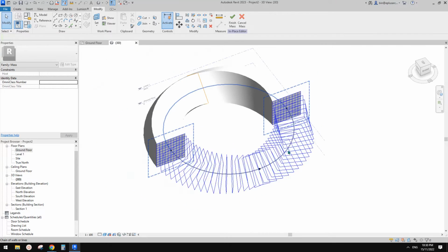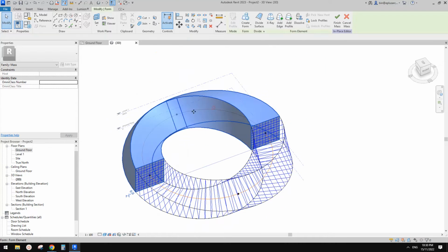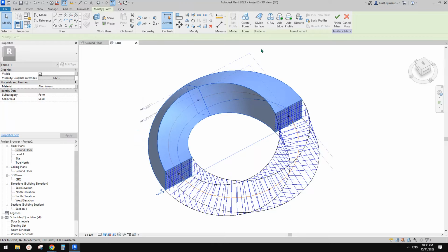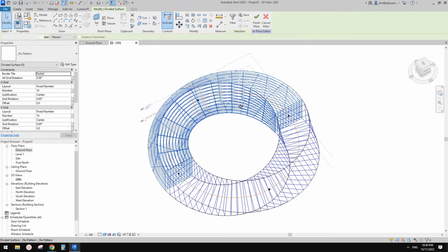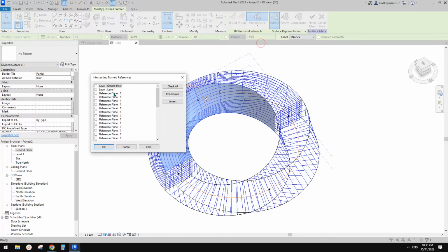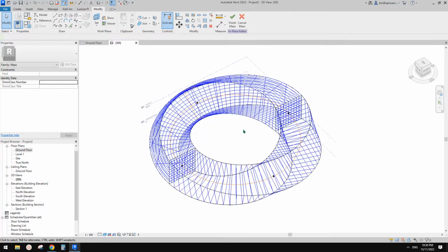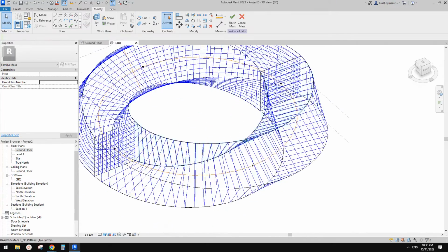And okay, so the next step, you can do it to the other side. So exactly the same, just the divide surface and select the surface, uncheck, and the list first, last, click OK. That's it, right? I'll skip that part. So let's go to the next part.